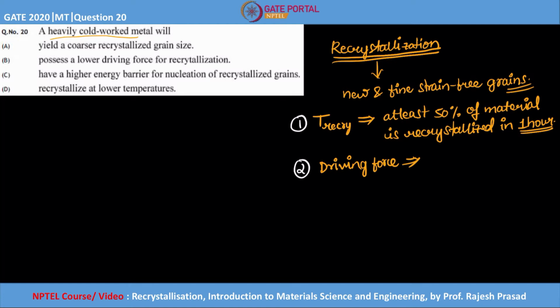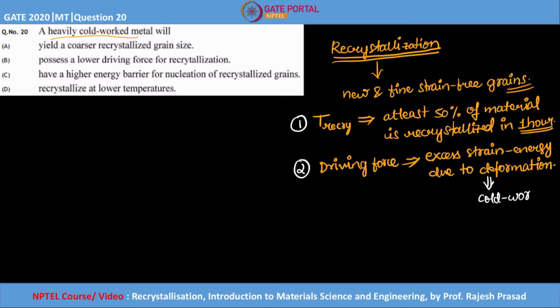The more energy associated with the system, the more the driving force, because the excess energy possessed by the system has to be reduced. So the driving force is nothing but the excess strain energy. We call it strain energy because it is due to deformation. In the question, what is the deformation technique? Cold working, because you deform at room temperature.